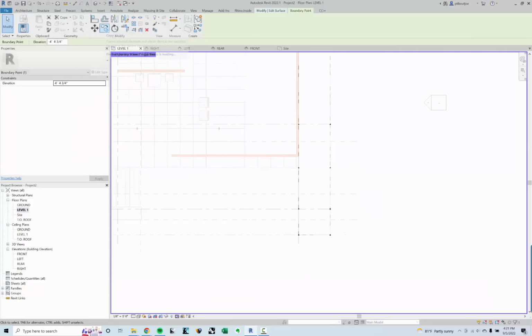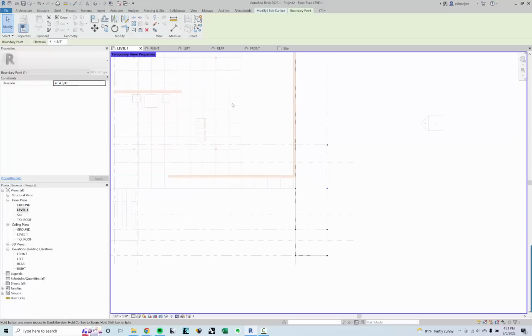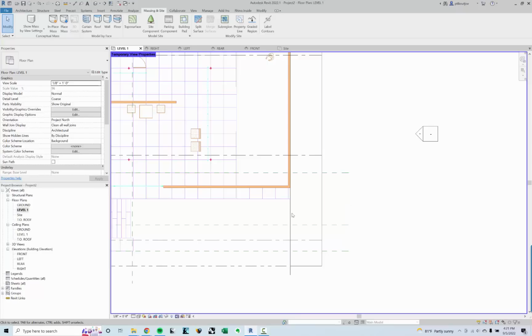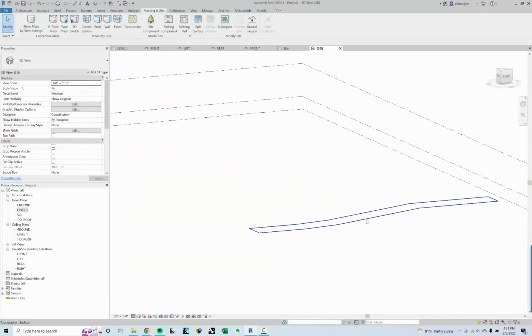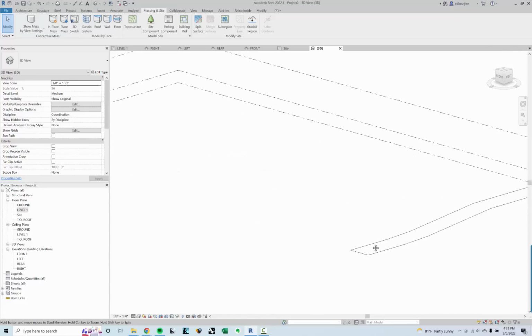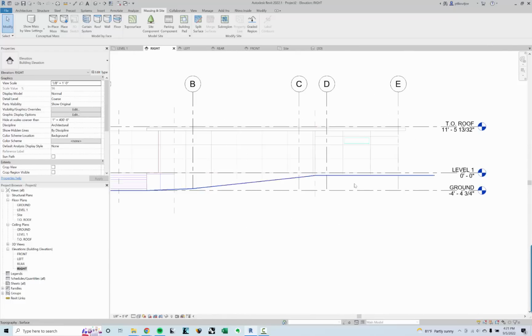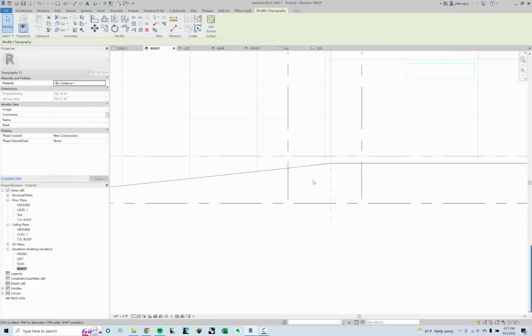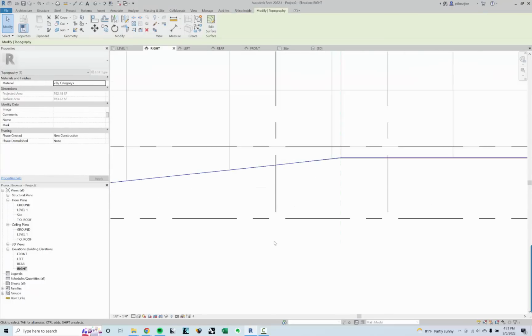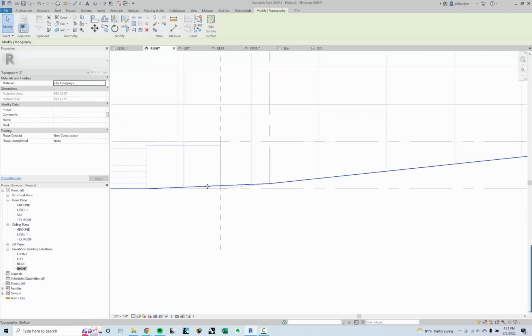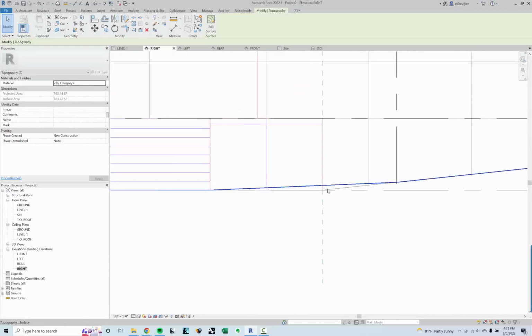And so once that's done, I'm going to click on Modify Edit Surface, click the check mark, and now if I look at this, I have a surface that's actually going angled up. It follows the surface of the topography on the side of the building, and I can even check that right elevation to see. And actually, that's the surface that I just clicked on. This is the topo surface here. And it's pretty close to what the line of the side of the building is.